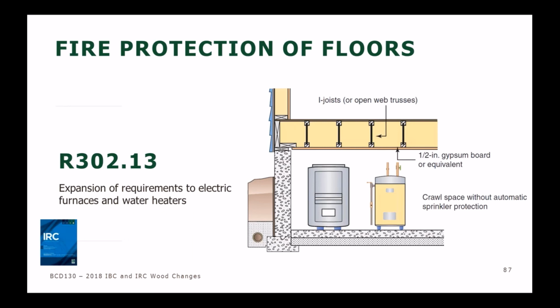Well, the change in 2018 was to say, all right, before these were fuel-fired appliances, so gas-fired or propane-fired typically across the country. Now if they're electrical appliances, they're also going to require installation of this 1/2-inch gypsum board. So it no longer really matters what fuel source or process to run this equipment it is. If it's in the basement, if it's in the crawl space, that 1/2-inch gypsum board is going to need to be added or something equivalent to it.